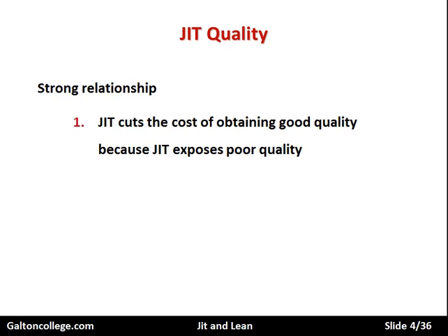The idea of JIT, just in time, is to try and look for good quality that arrives in the production area just in time for production. It's not wasted capital, it doesn't go into the stores, so deliveries don't go to stores, get booked into stores, wait in the stores, are then booked out by production people and produced.